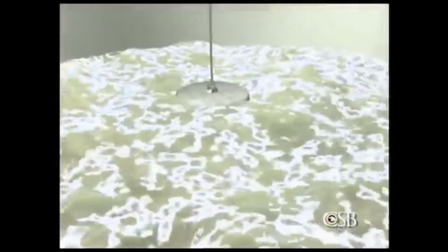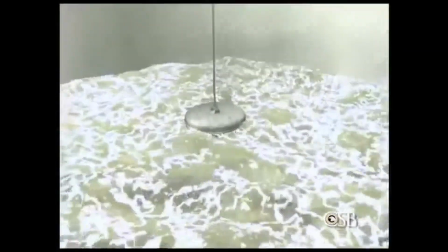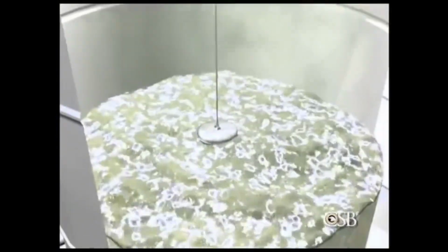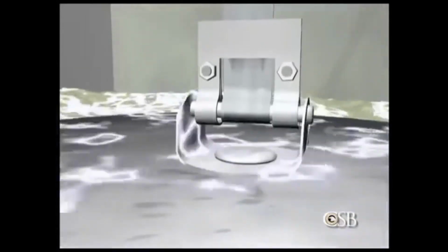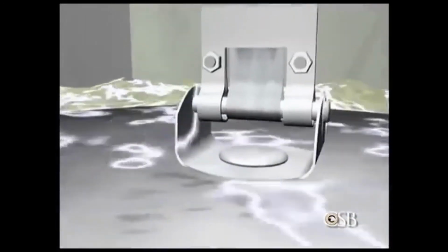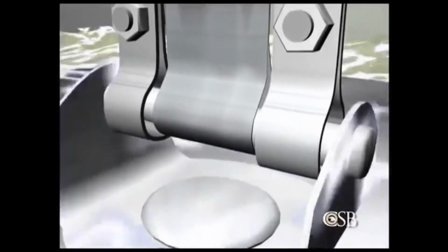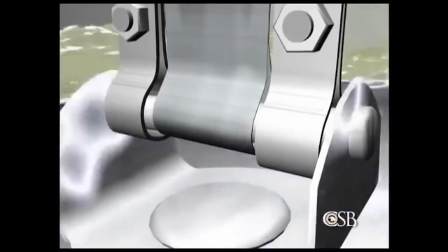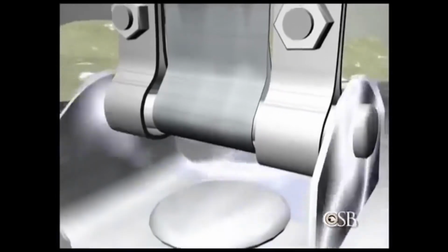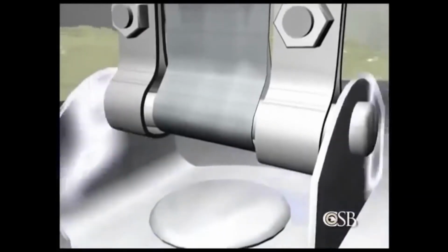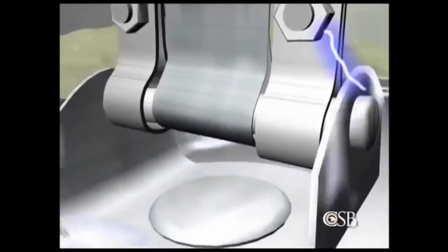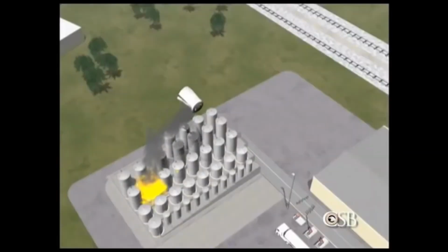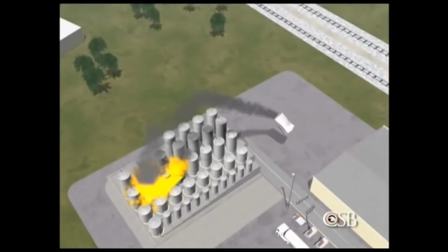Meanwhile, the space above the liquid was filled with an explosive mixture of vapor and air. The swirling, turbulent liquid caused the float to drift and rock, creating slack in the metal tape. This allowed a gap to form intermittently in the linkage assembly, interrupting the grounding of the float. The metal float accumulated a static electrical charge. About 9 a.m., a spark from static electricity ignited the vapor-air mixture, causing a massive explosion.